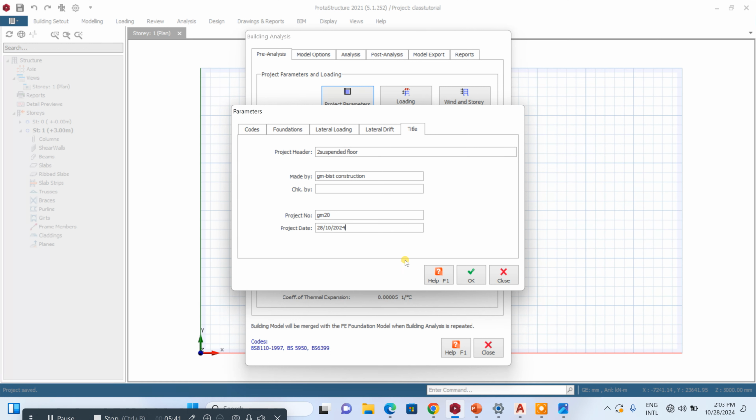So the architect actually did not position this on the wall, so we are going to offset this. Click on it, offset here, then you offset this one. If you want to offset, it's Ctrl F2, then half of 225 is minus 112.5.